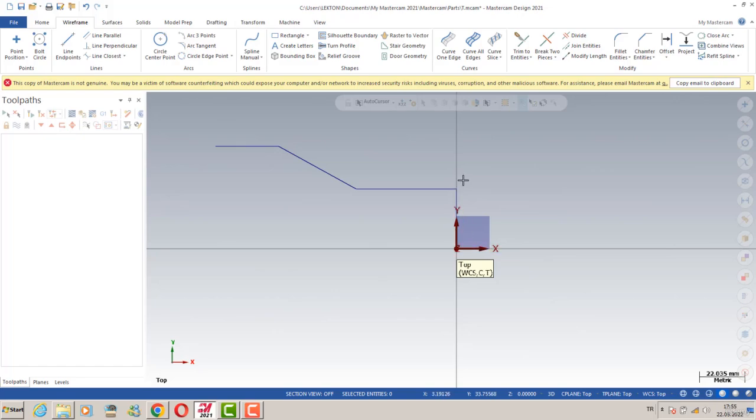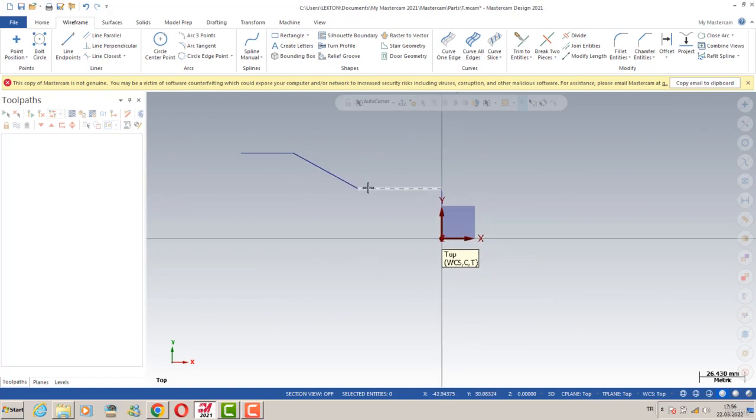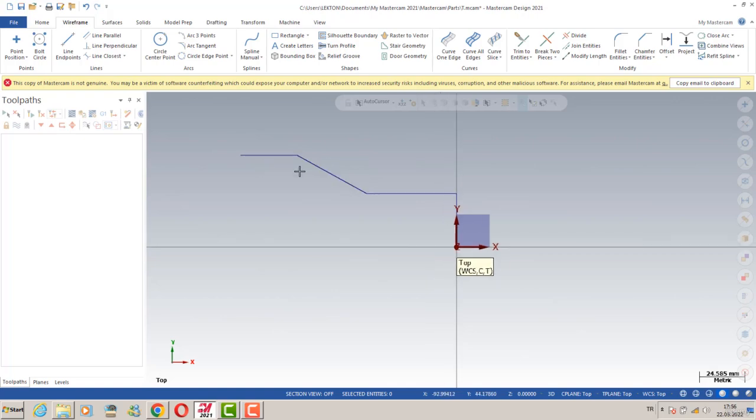So when we turn the lathe mode, we're gonna see that this is the X-axis and this is gonna turn to Z-axis. Okay, so at that point I don't care about the axis X or Y. We already know that we need to focus on that area. Okay, so this is the two axis lathe process.